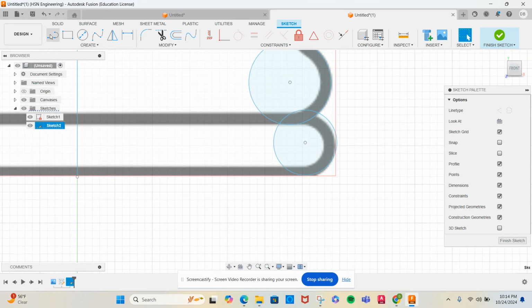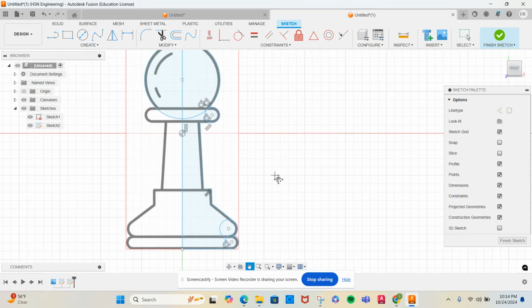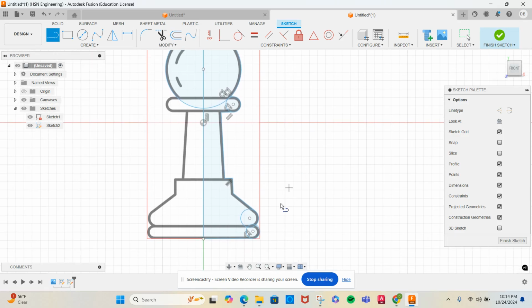And then we're going to take a straight line and connect the bottom of the circle here. Again, X marks the spot. Get that blue X, connect it to the bottom of this line. If you went below here and you just connect it so it's horizontal and there's a little extra in there, we're going to trim some stuff anyhow, so that would be okay. See how that changed color? It went to blue. That's important to see. You need connected external lines, and you need things to turn blue for this stuff to work.